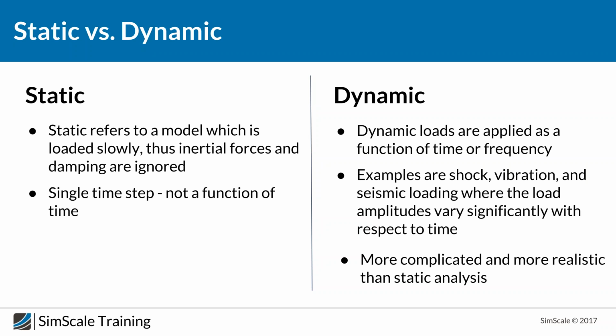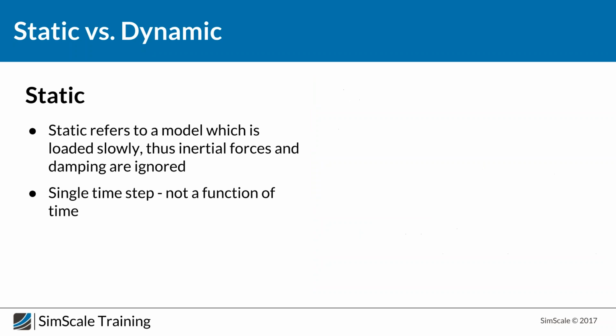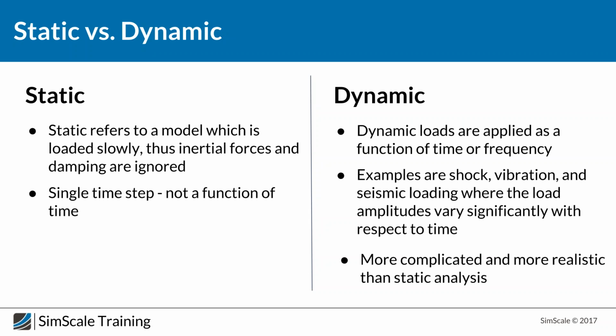It's more complicated and more realistic than static analysis. As I said, static is just a very simplified special case of a dynamic simulation, but every time you should go with the simpler version. So if it's possible, go with linear instead of nonlinear, and if it's possible, go with static instead of dynamic.